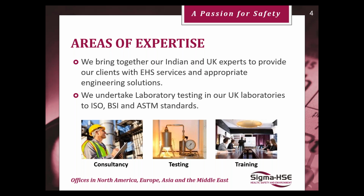We also undertake laboratory testing. This is, for example, your onset temperatures, your flammability data, your explosion severity data. It's quite relevant to today's topic because with this testing data, you can ascertain the correct equipment. For example, temperature class, the maximum allowable temperature, be it in dust form or in vapors form. Also explosion severity. So when you buy your explosion panels in your dust collector, for example, it is suitably rated to certain values, for example, a maximum pressure rating, a KST value.